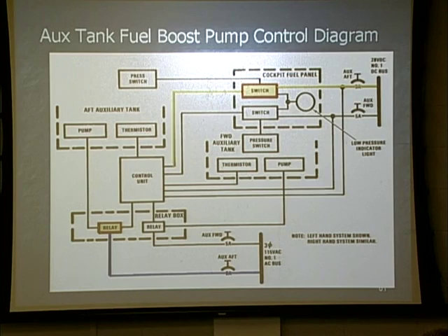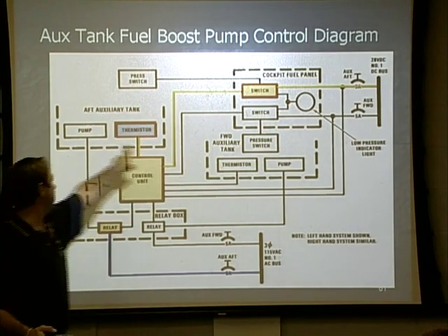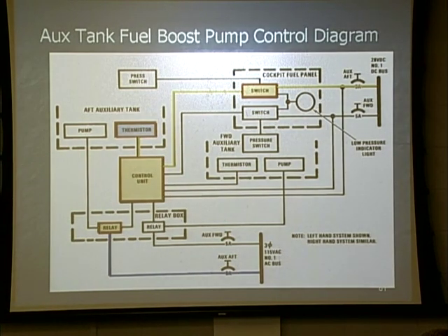But now what's going to happen is it's going to go to that control unit that's located at the top of that relay box, and then it's going to go to the thermistors and check it. Right now, because there's no fuel inside that tank, it's not going to allow power to go back and turn the pump on. If we were to put fuel in that tank and now cool it down, the thermistor is now going to send through the various relays, and now it's going to allow the pump to turn on. Any questions about that? That's all that this is showing.